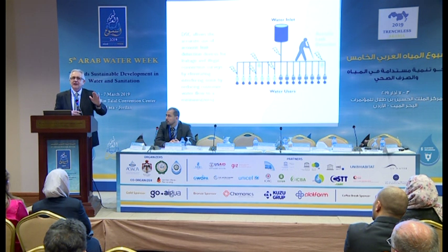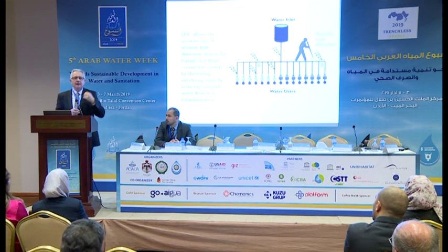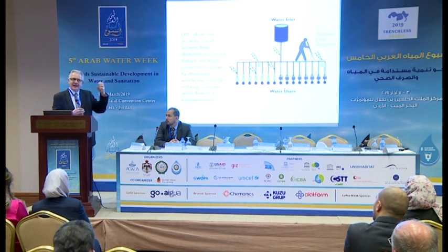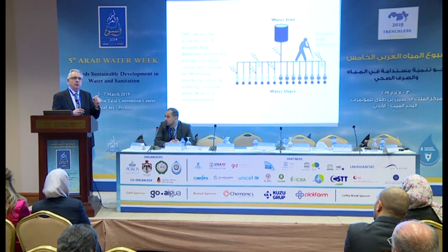We are not supplying to the customers, so we have no noise from water going through the service connections. So mainly the noise will come from the existing leaks. So active leakage control is actually possible under this condition.